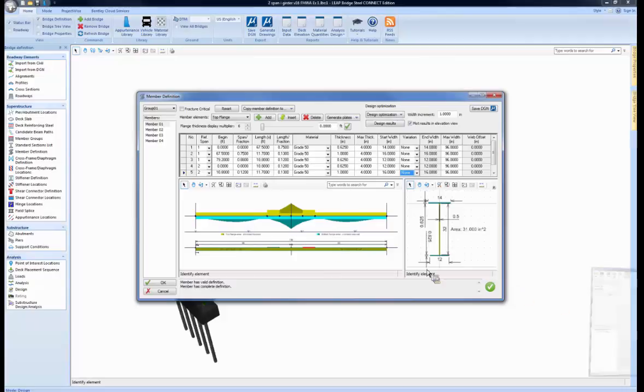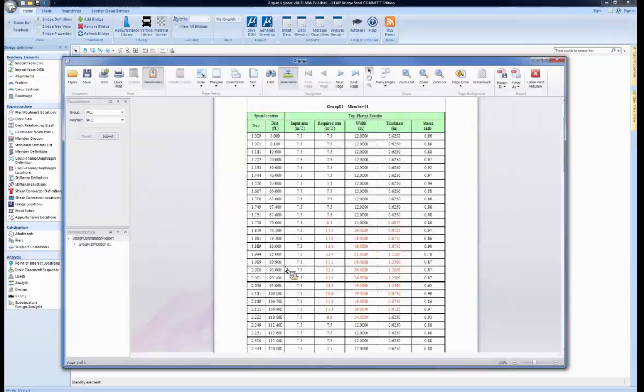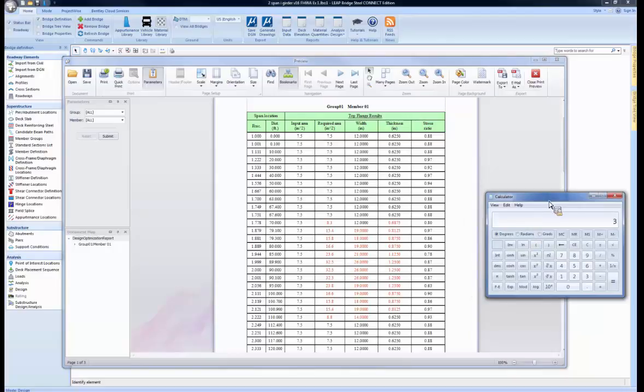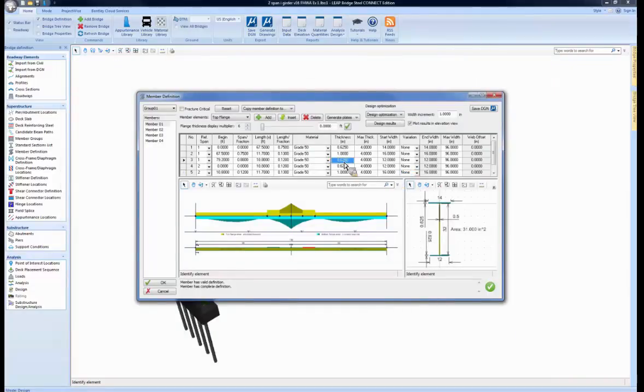And then lastly, right over the support itself, we can see it's calling for an overall area of about 32.5 inches here. And I could go up to as large of a plate as it's calling for there, but maybe we'll try something different. So we'll say 32.5 divided by maybe an 18-inch wide plate. So that comes back with a greater thickness of a little over 1.8. So I'm going to go back into here, and I'll say maybe we'll make that 1.875 and 18 inches wide.